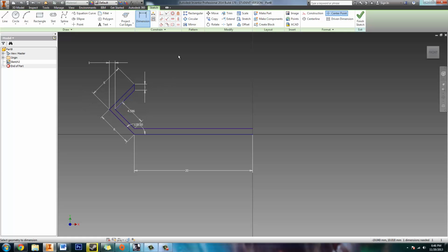Alright, now that that's done, I'm going to mirror this wall of the racing track and place it on this side. To do this, I need to select the line tool. I need to make the line a construction line, so selecting construction line, and I'm going to place it in the center of this line. It can be any height you want. Just make sure it sits at 90 degrees, and then left click.